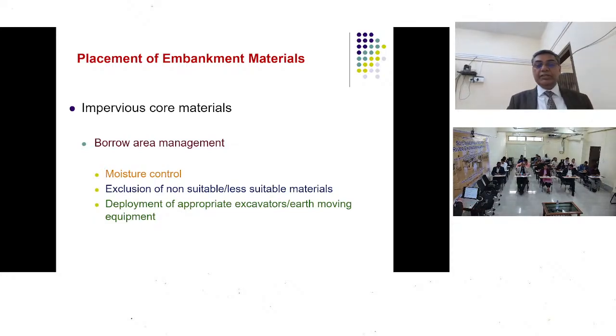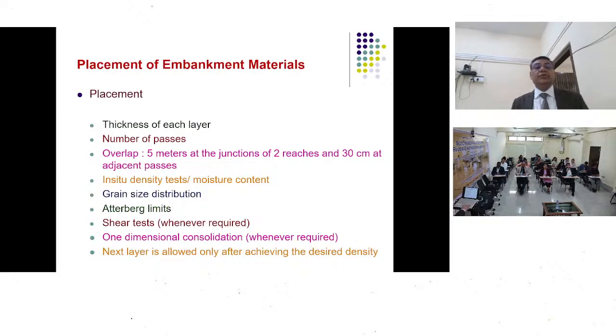Then exclusion, as I was saying, deployment of appropriate excavators or earth moving equipments that you have to see. During placement: thickness, number of passes, overlap. 5 meters at the junction of two reaches and 30 centimeter adjacent passes.